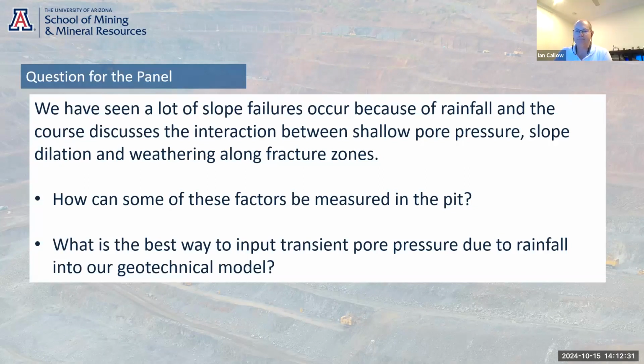So if a piezo is dry, that's information in itself, and you need to ensure that the monitoring of that piezo just continues, and it's just not disregarded as a dead one. And the same probably goes for the drain flows. Again, the data is key. Measurement of flows, even just an anecdotal visual measurement of flows, if you can't physically get to a drain safely.